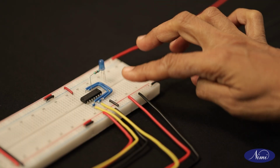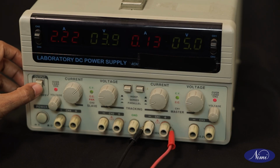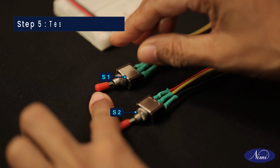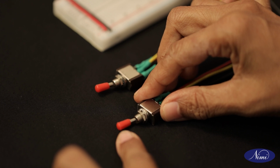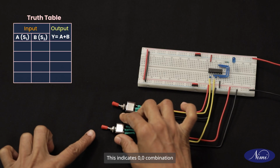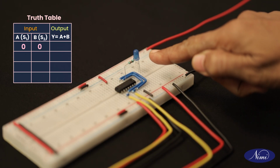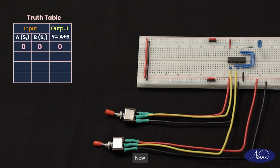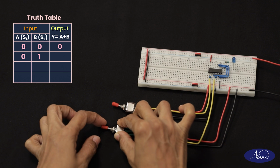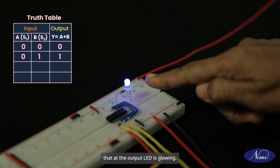With everything checked, switch on the 5V DC supply. Begin the test by operating switches S1 and S2. Check if the toggle switches S1 and S2 are in the low state. This indicates 0-0 combination. For this, let us verify the LED. It is not glowing. Now, toggle the switches to 0-1 combination. Verify the LED. You may observe now the output LED is glowing.